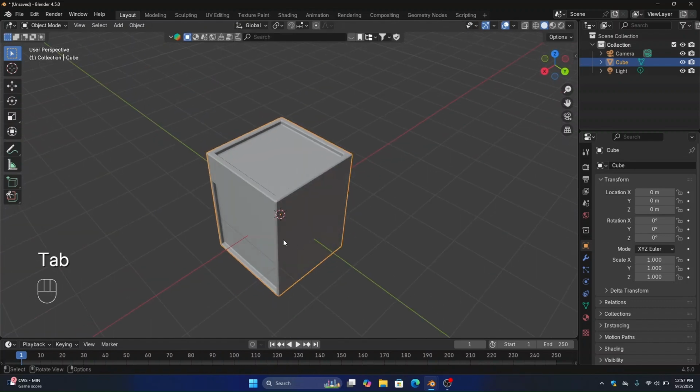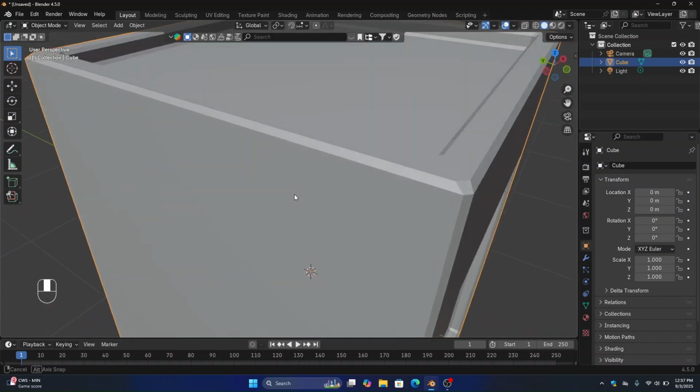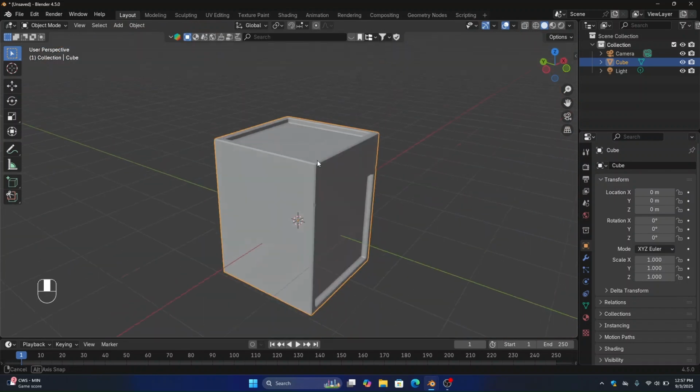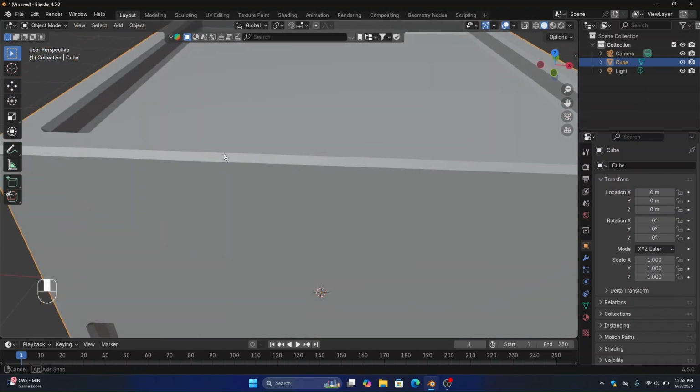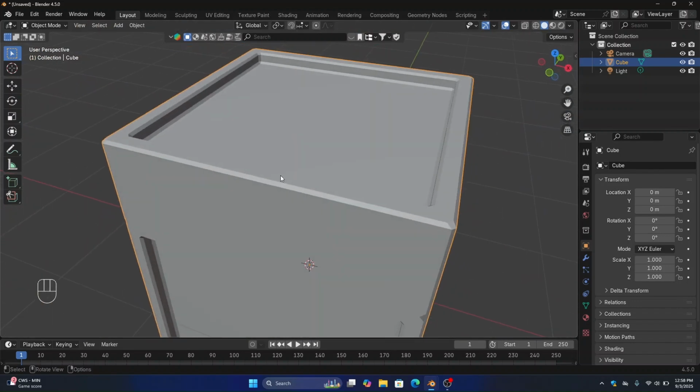And now you are able to see there was a difference before and now it's a little bit different. Now there's an error; we will fix this topology and then you are seeing the difference after the bevel tool. What the bevel tool does is add a little bit of geometry to your object and smooth it, a little bit or as much as you want.